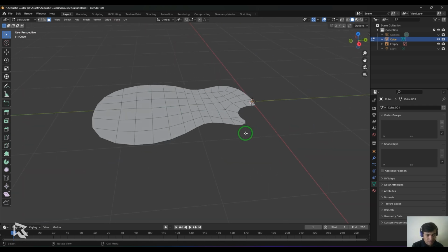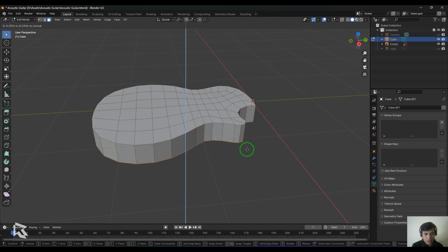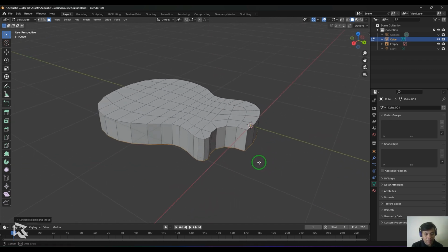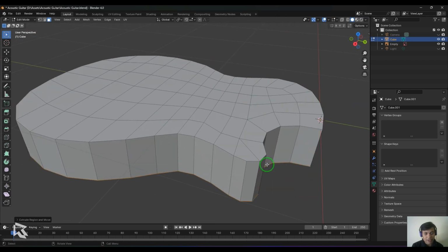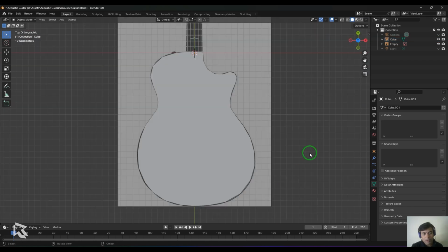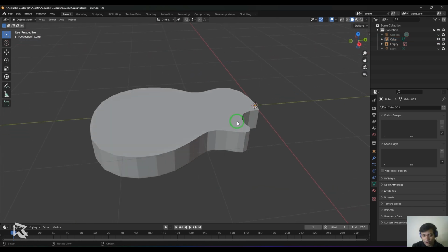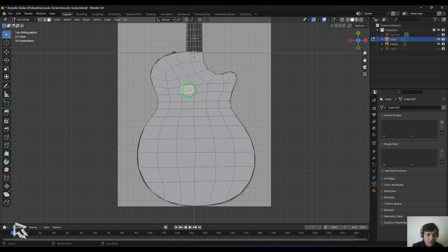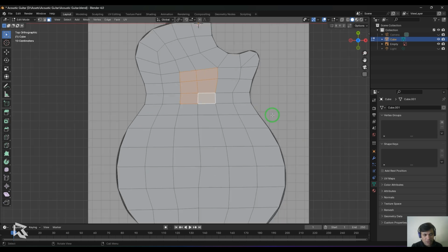I select the faces, press A and then E, and then extrude it, which goes on to the bottom side for the thickness part. So this looks good at this point of time. So I have this model got the solid shape here. So I just wanted to punch a hole, a circular shape hole in this center. So I go to the top view, select the model, press tab, press 3 for the face selection, and then select these 6 faces which are around the circle.